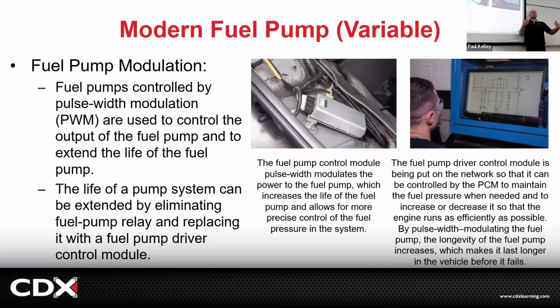Now it's like, what signal is the fuel pump getting? Did you catch that? It's not getting just 12 volts, it's getting pulses. So if it's getting a pulse width modulation, we need to verify, is it getting the right pulse? That's going to be a little tougher. I mean, put a scope on it. The scope is actually a really good diagnosis tool for the fuel pump now. You can see the waveform and see, is it getting an on signal and an off signal, an on signal and an off signal. So even this modulated fuel pump diagnosis is going to be a little more tricky, right? That's kind of the point.